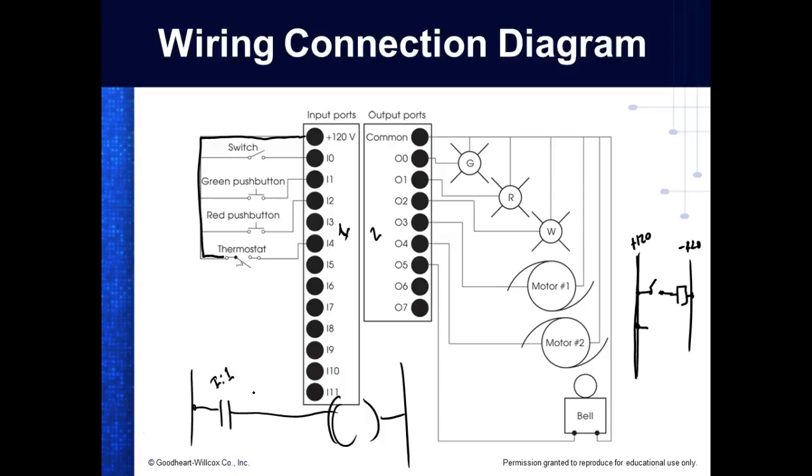If you're in a modular PLC, so if you get on one of the 504s, when you create your program, you're going to have to specify those input and output modules. It's no big deal. You're going to have to specify the size of the rack. So how many slots do we have? We've got 7. We're going to say, okay, it's a 7-slot rack, and then numbers will pop down in there. It says 0 through 6.